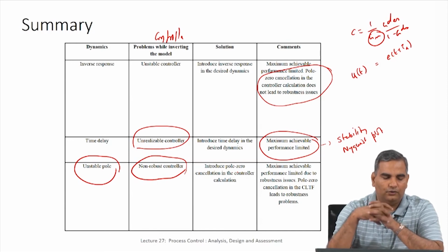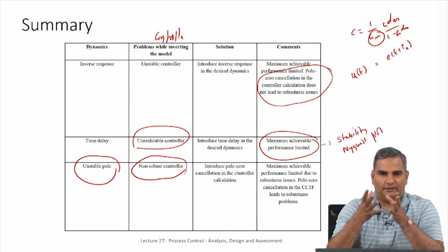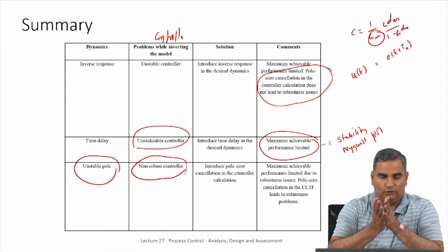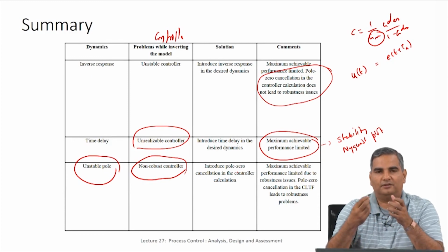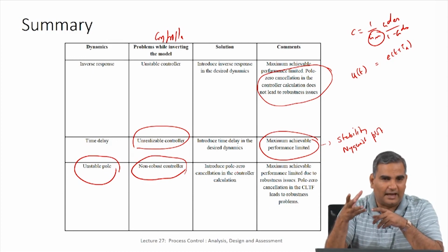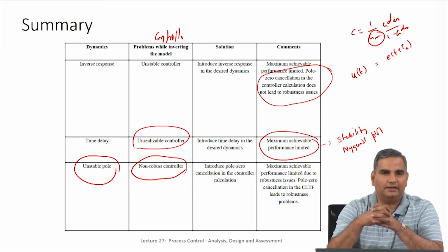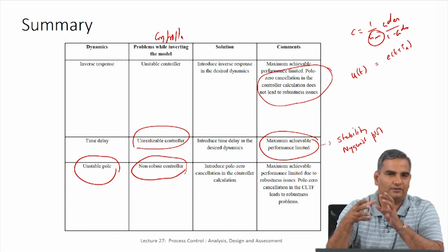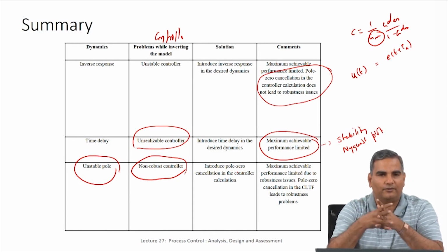However, when you do this direct synthesis approach for controller design and start understanding this, then if you say my gold standard is G desired, and if there is a process which allows me to choose G desired any which way I want, then I would say that process is not limiting me in any sense. It is not the actual G desired itself, but the choice of G desired should be completely up to me, in which case the process does not limit me from choosing any G desired. So, I would say there is no performance loss.